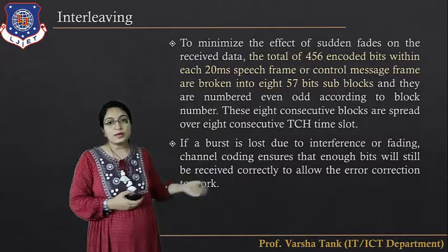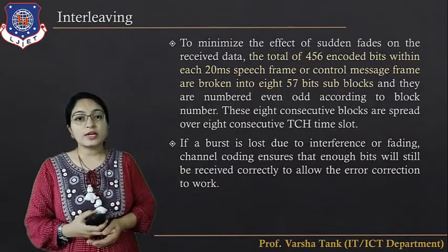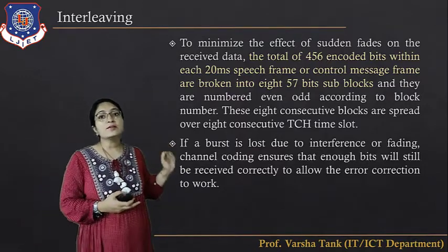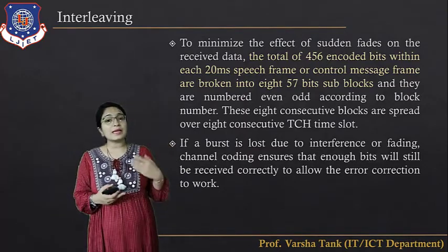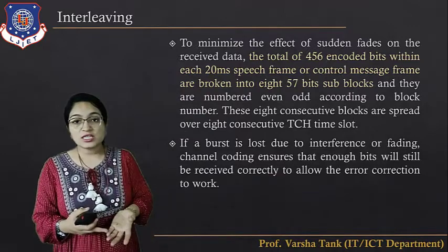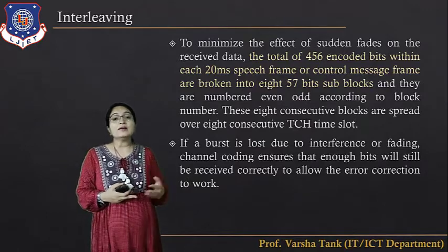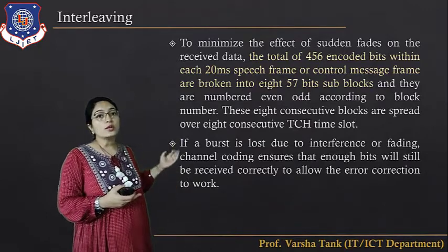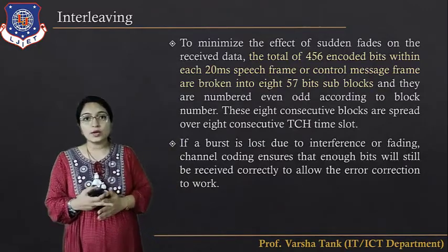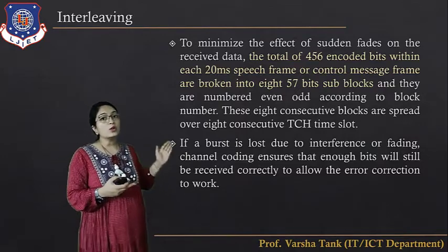Now, interleaving. What is the meaning of interleaving? To minimize the effect of sudden fades on the received data. Sudden fades mean there may be some atmospheric effect, or some data change can occur. So to minimize this effect, interleaving is performed.